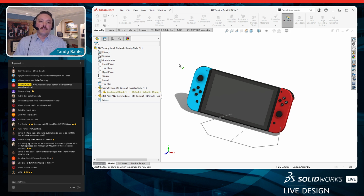But if you'll notice here on the screen, hanging off of my mouse cursor is a little check mark. And anytime it doesn't automatically pop up the way that I think or what I'm expecting, always look at the status bar. The status bar is at the very bottom, right below the feature manager area, and it's letting me know that it wants me to select a face to place the component. And whatever face or plane that I select is going to become the front plane of my new component.